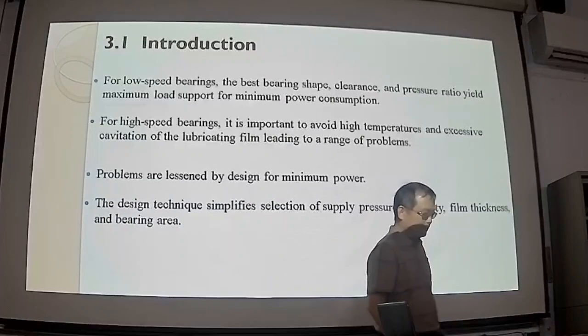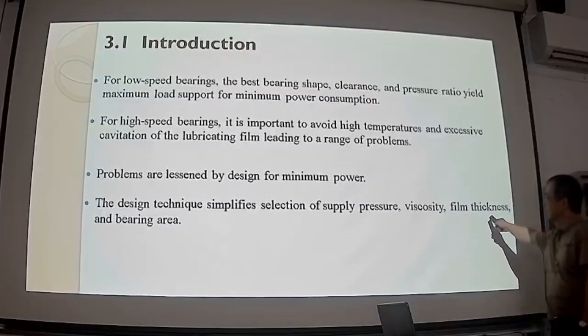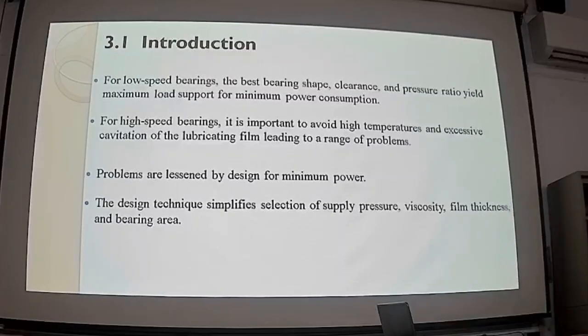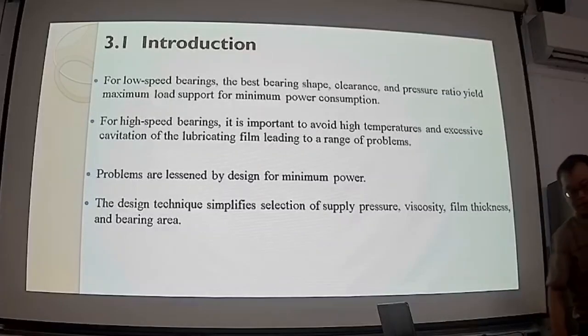And the film thickness is also easy to decide. Usually this is decided by the skill of your assembly worker. So what is the minimum film thickness that your company's assembly worker can put together for a hydrostatic bearing? The oil film gap is not too difficult to decide, but you cannot choose too small, otherwise the assembly people will tell you it is very hard to fit, half an hour and still cannot get it in. You should pick the right film thickness.